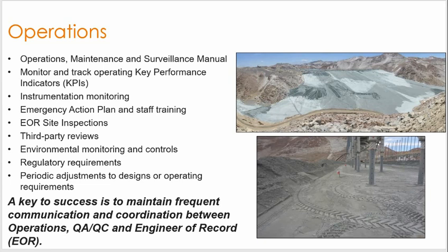I mentioned earlier the term engineer of record, or EOR. Every tailings facility has an EOR, and that's a person who's usually supported by a team who essentially acts on behalf of the design of the facility. So when I talk about myself offering design and operational support, my direct supervisor is the engineer of record for these facilities in Peru. There's a lot that goes into being an EOR and supporting an EOR. Part of that is that the EOR performs usually quarterly, perhaps monthly, site inspections, again tracking those KPIs and making sure that things are proceeding as intended.